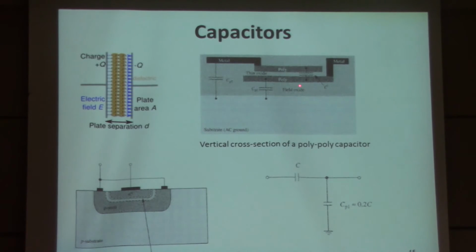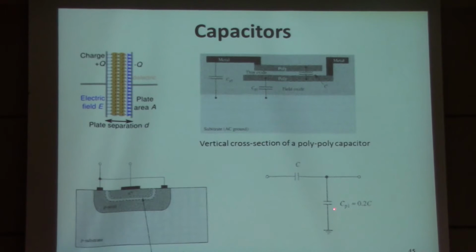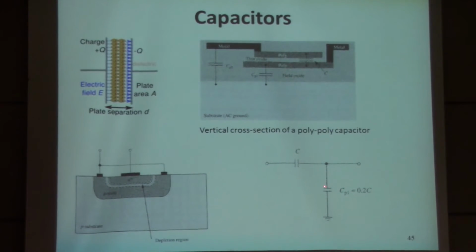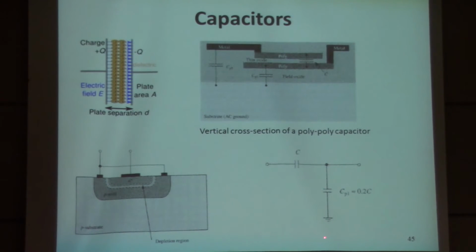Because, for example, your bottom plate, or one electrode, will always have parasitic capacitance to the ground. So at a very high frequency, this one could short circuit your output. So how high can you go? Then what kind of geometrical arrangement can you make, so you can make it go higher?